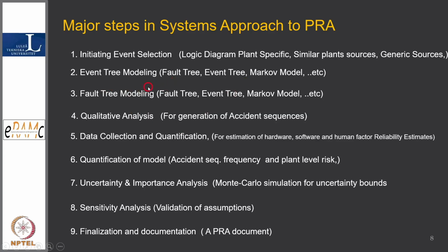Inventory modeling. After the initiating event, the next stage is inventory modeling. It is actually a qualitative modeling. So we use the tools fault tree and Markov models. These are the tools we use for inventory modeling. I would say prominently fault trees are used for inventory modeling, and Markov models to support certain frequency. If you want to analyze with maintenance, without maintenance, a complex situation, then we use it.